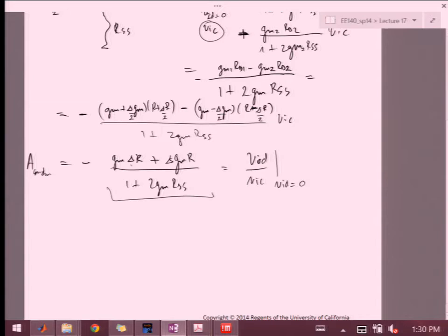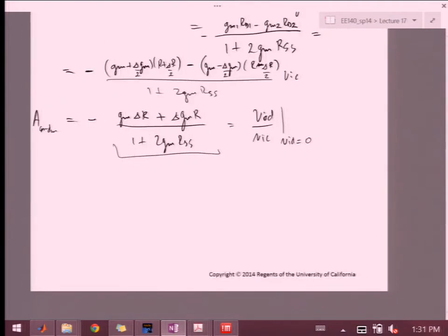So this essentially depends on the delta in R and also the delta in GM. Delta in R and delta in GM are actually of opposite polarity, but delta GM is damped by the square root of the current, because the delta in current and delta in R are linearly proportional, right? We said that the current times R has to balance on both sides, right? That was the first thing we derived today. So this is still a non-zero component.